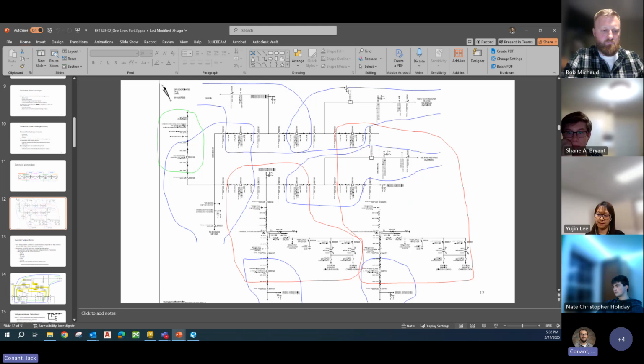I know it's kind of hard to see, but you can see this line comes in between these two breakers, right? So these two breakers are the interrupting devices to protect the line. So we wrap those two breakers in our zone of protection. And that way, the relaying for this line trips those breakers to interrupt any faults on this line, right? The transformers are a little different, right?